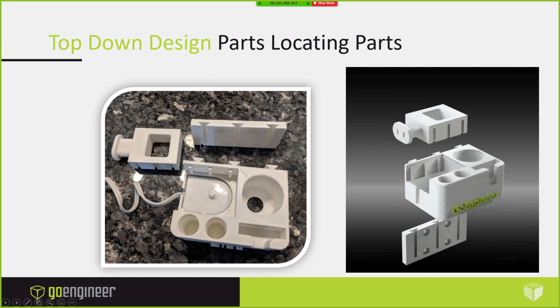And then for top-down design, I started with this plate, and then I created a little device here that was built off of this plate. So I used, if you guys are familiar with it, offset entities, and I did, I don't know, like a 1/32nd offset, or no, it's probably 64th. I'm always working in fractions. Made a little clearance so this thing can drop in there pretty nicely.